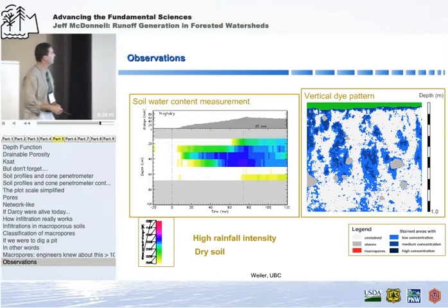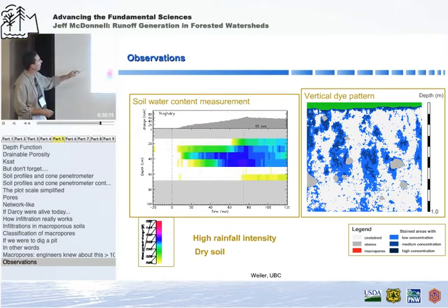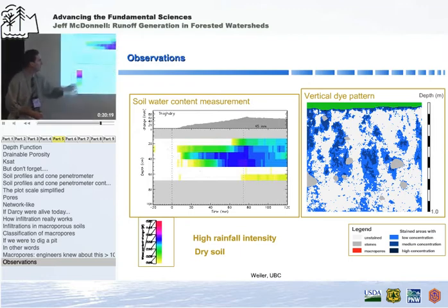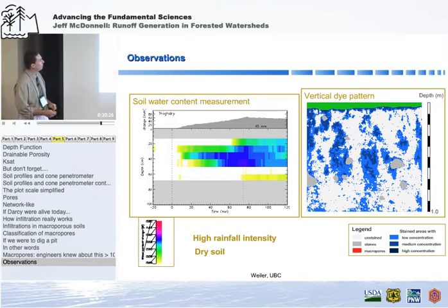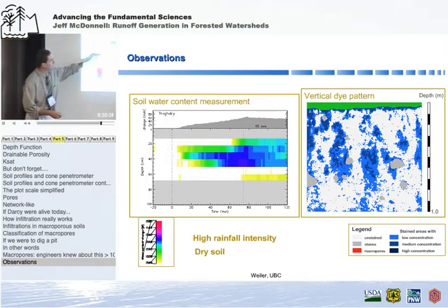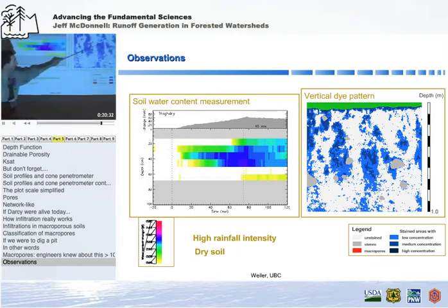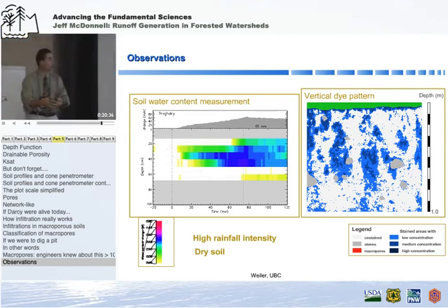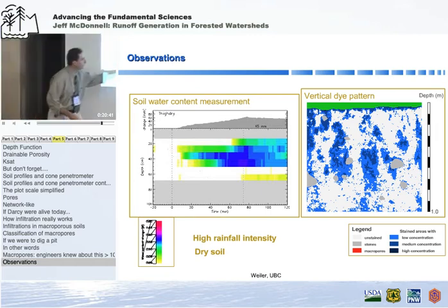Here's some more data. I'll just show you one or two more slides. This is now a series of TDR rods going from the beginning of this wetting event through to about 2 hours. These TDR rods are installed horizontally at these different depths down through the profile. And this is showing how the TDR is measuring, because they were installed in this center of mass of preferred water movement to depth, but of course are not seeing what might be happening elsewhere along this area.